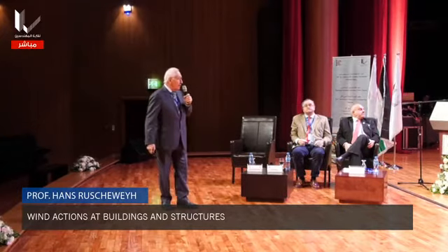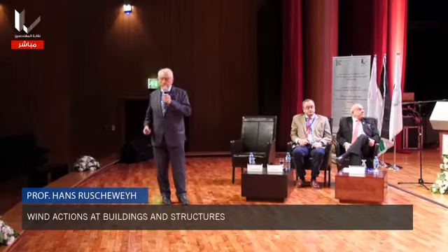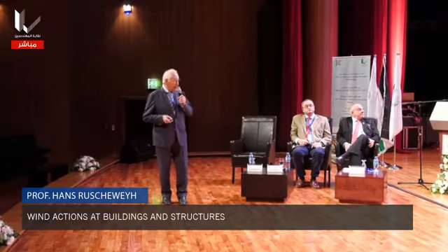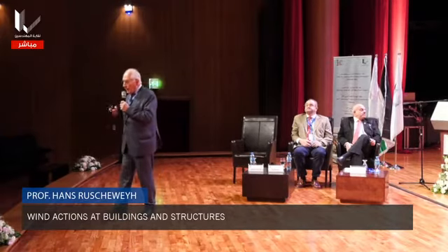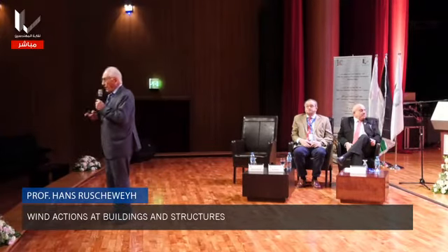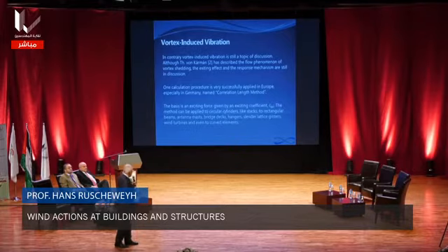The basis of the exciting force is given by an exciting force coefficient. The vortex shedding causes exciting forces. Some people speak about aerodynamic damping. This is not correct. The correct situation is exciting force. And the exciting force produces resonance responses.